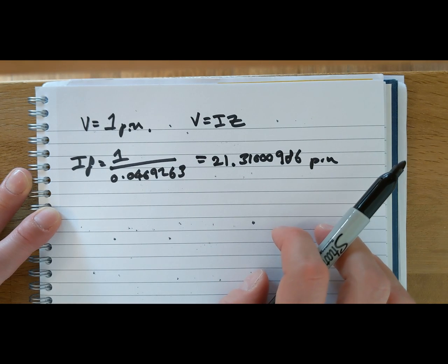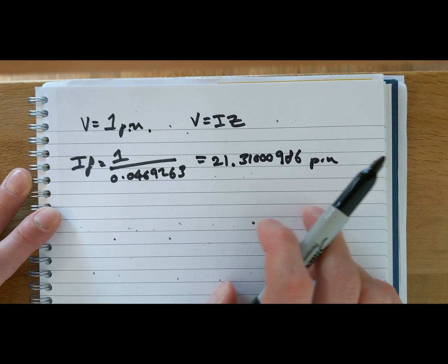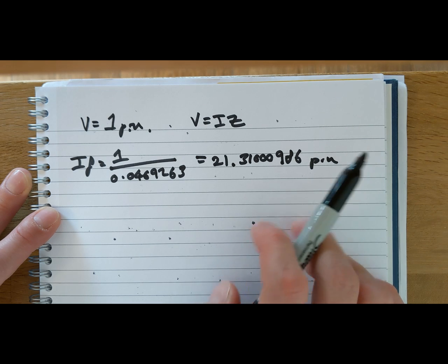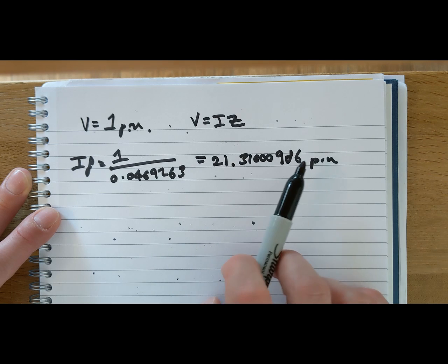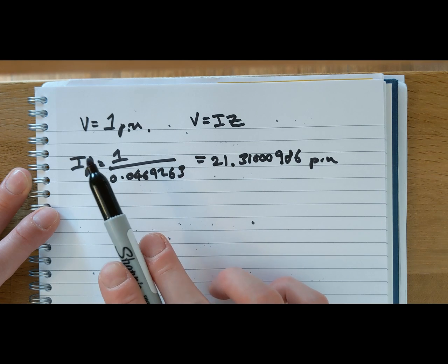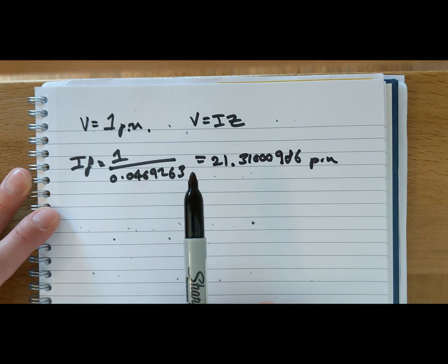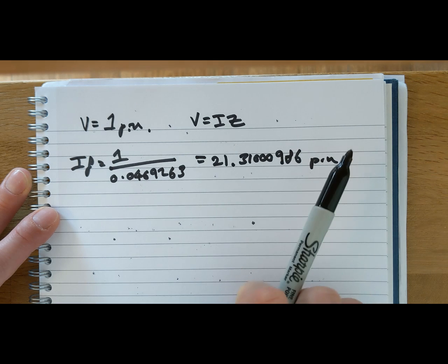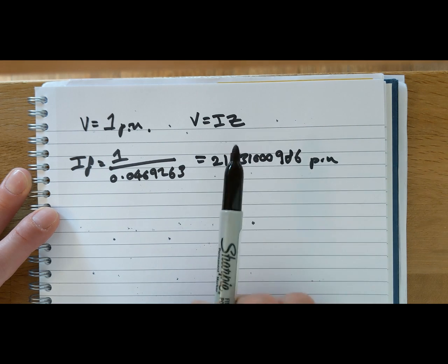Because as we were saying earlier, as the turns ratios have been taken account of in the bases, this is actually the fault current through the entire system in per unit. We don't have to reflect the fault current by the turns ratio to get the appropriate fault level at each and every point, because this value in per unit is the fault level throughout the whole system.